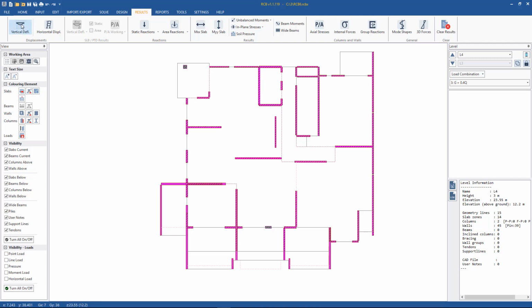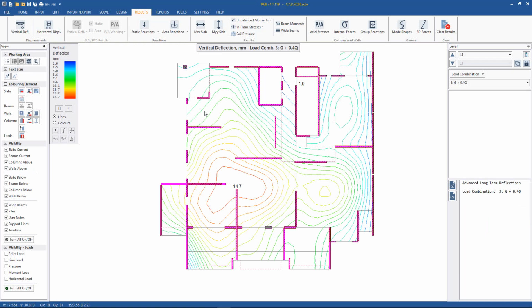Currently the model has essentially come into existence in one go. However, with construction stages, with construction leveling, this particular floor will be constructed flat. It won't be constructed on the displaced shape of the level 1 slab.